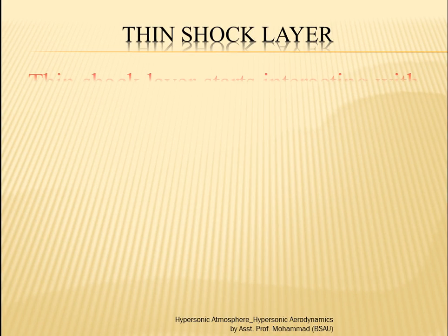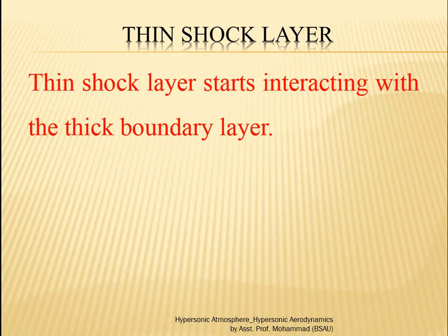When the thin shock layer becomes thin enough to be comparable with the thick boundary layer growing over the solid surface, the situation becomes a little bit complicated, because the thin shock layer starts interacting with the thick boundary layer. This interaction is another specific phenomenon which normally occurs in hypersonic flow only, because the shock layer becoming comparable with the boundary layer is possible only if the Mach number is very high and the wave angle is very low.